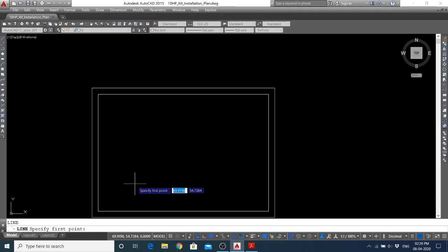We can move the mouse on the screen to change the coordinates and left click to start the line, or we can specify the coordinates through the keyboard, but that is difficult because it is hard to know which coordinates to choose. So we will just left click on the mouse.